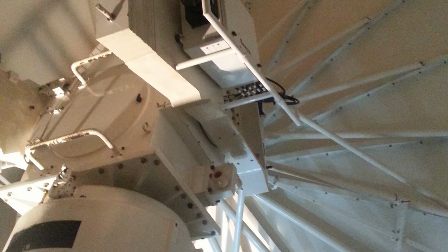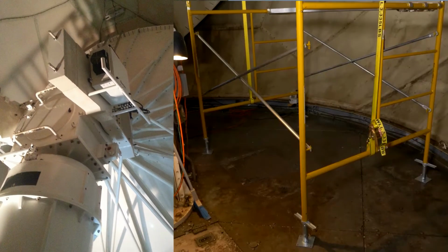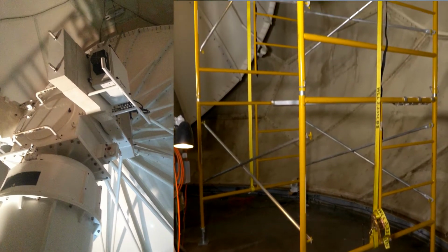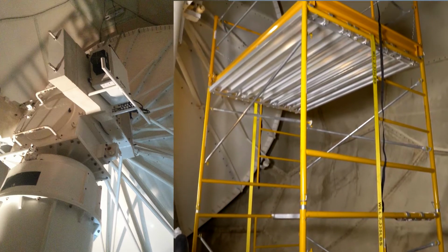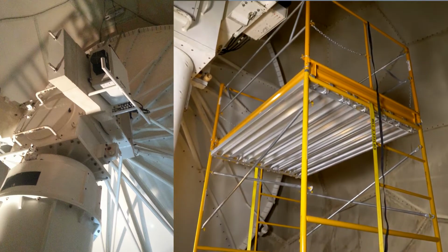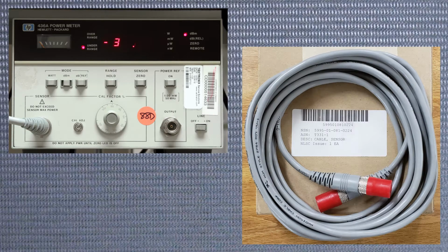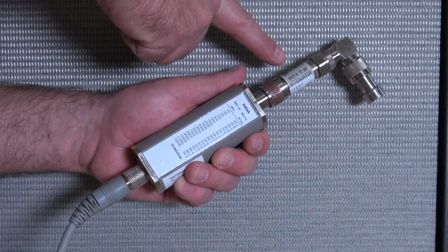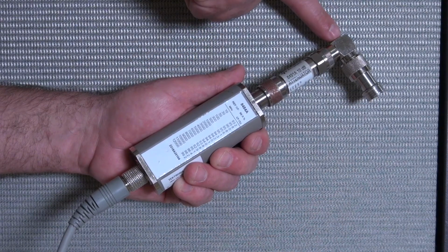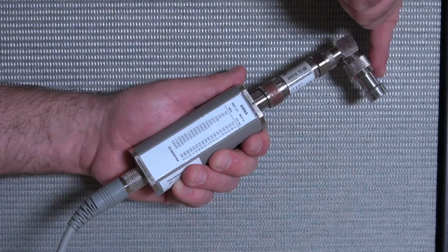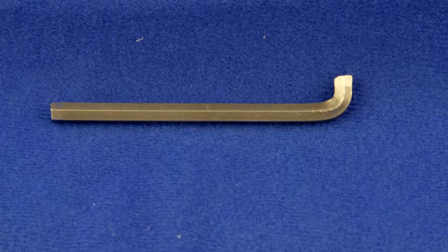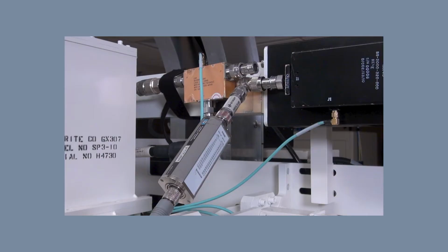FaultNet 69 steps 1 through 21 should be completed. The antenna should be stowed at 23 degrees and a ladder or scaffold positioned to access 2A5DC3 and horizontal TR limiter 2A5A1. This procedure requires a power meter, 20-foot power sensor cable, low power sensor, 10 dB attenuator, 90-degree Type N adapter, Type N female to QN male adapter, a 3/16 Allen wrench, and tie wraps or Velcro cable ties to secure the LNA when disconnected from the TR limiter.